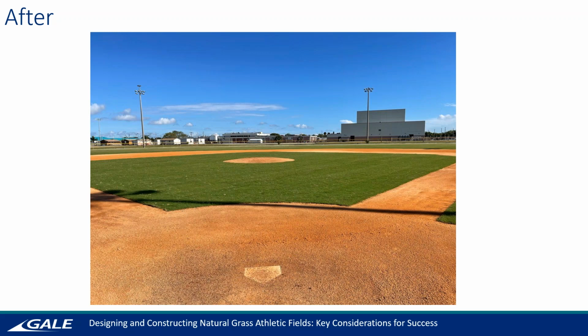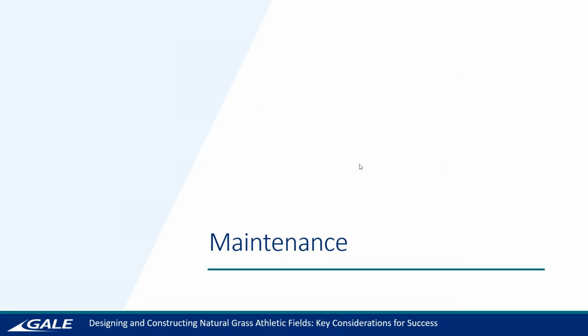They still used the soil, but they amended it. But they did include a new subsurface drainage system throughout the whole field, and then re-laser graded the whole thing. So it came out to be a success. They scraped off and installed the larger safety runout area, and it's performing as it was originally designed.